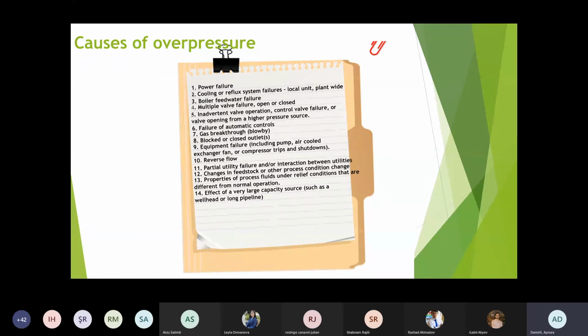In these circumstances, it may not be feasible to provide a relief system of sufficient capacity to accommodate the case in which the high pressure system is suddenly de-isolated, for example, through failure open of the main equipment shutdown valve,